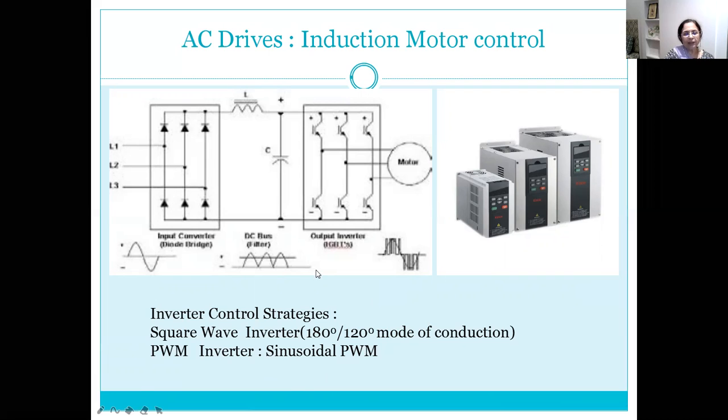So controlling the induction motor by stator voltage control as well as V/F control is possible, and the drives which utilize such strategies are called AC drives. They are very popular. Typically, the AC drives look like this. This is a configuration which can be used in general.